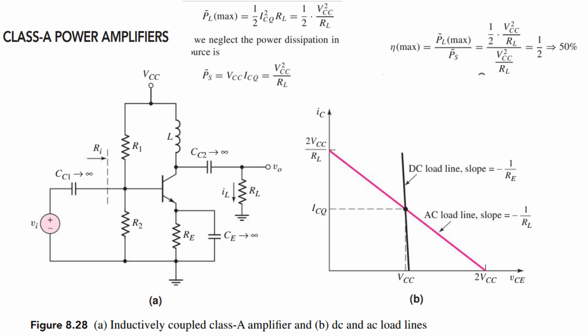Here it's very similar to the regular class A amplifier. The major difference is that now we are dealing with higher power, and Pmax can be utilized with different couplings. Here the example is shown using inductive coupling. Similarly, instead of the inductor you can also use a transformer, which is called transformer coupled, and so on.